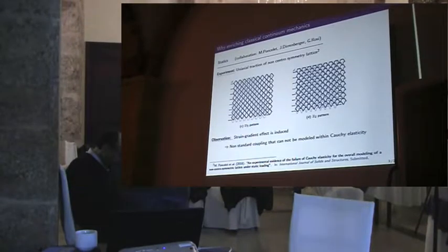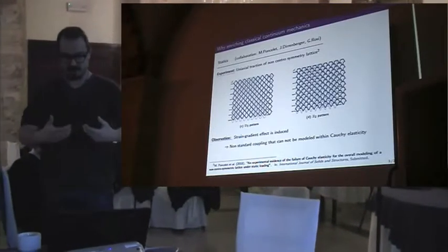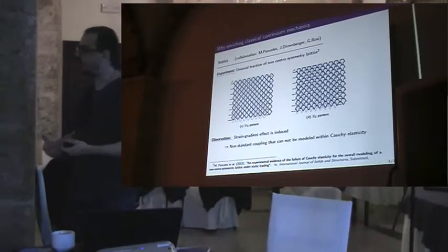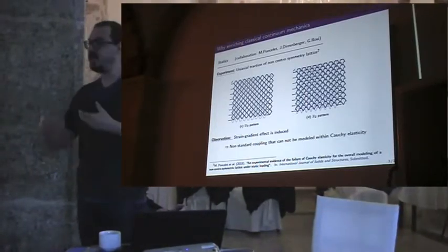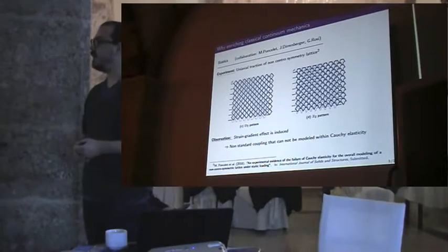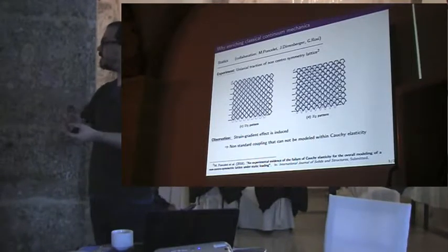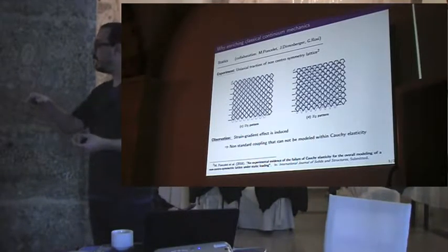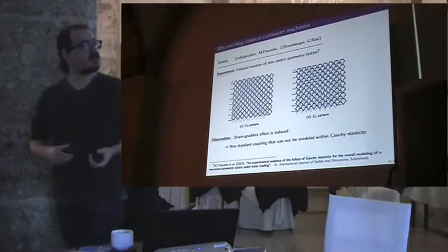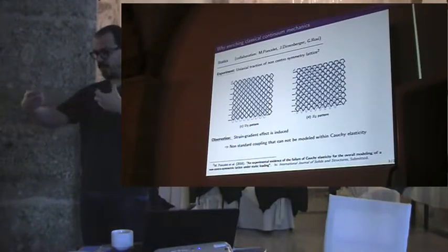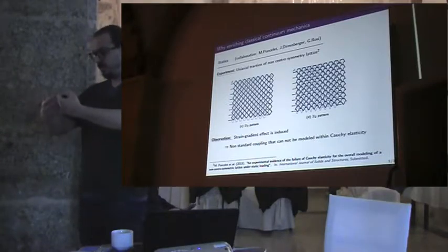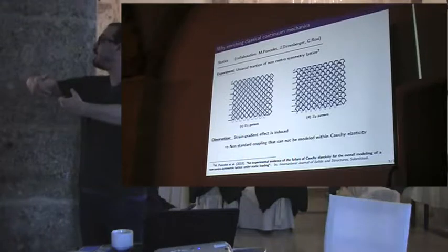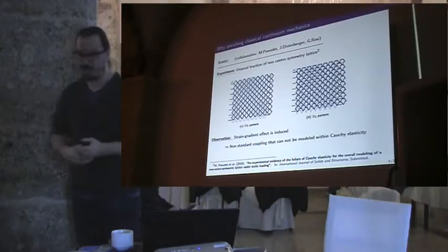Another point that may be discussed by Martin Poncelet tomorrow is an experiment that has been done in statics, in which we test a beam with a coarse inner structure, and we look at the influence of central symmetry in the pattern. If we have a coarse inner structure and we load it in tension, if the pattern is non-centrally symmetric, we have the appearance of a spurious bending displacement.